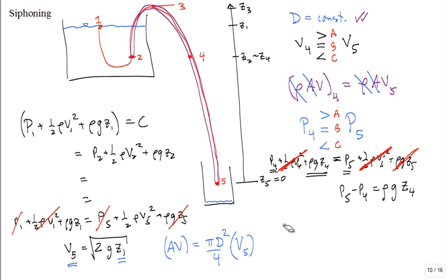It's a slight vacuum. So if a little mischievous person came and drilled a hole in 4, I'd like to ask the question: does the air on the outside of the tube rush in, or does the water or the gasoline or whatever liquid you're siphoning on the inside of the tube squirt out of the hole? Air is going to go in. It'll break that siphon.